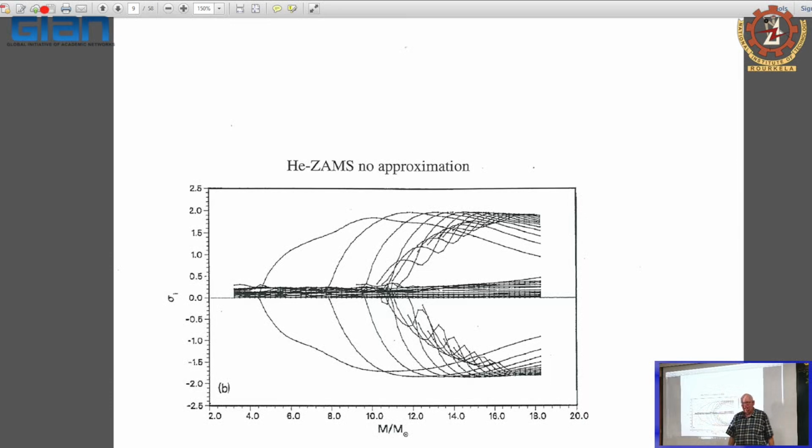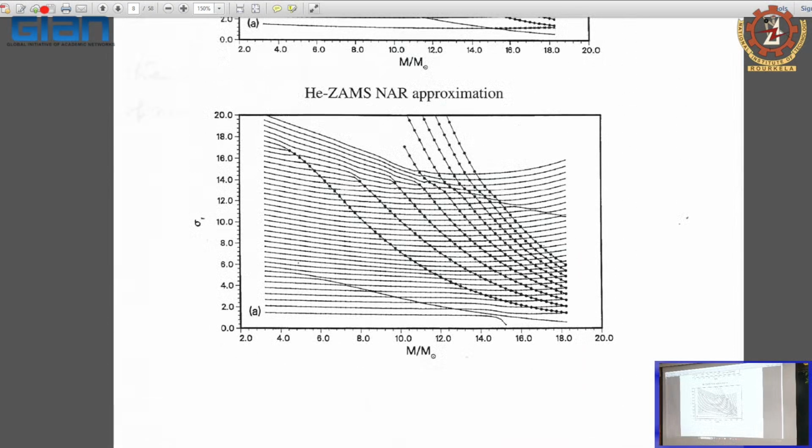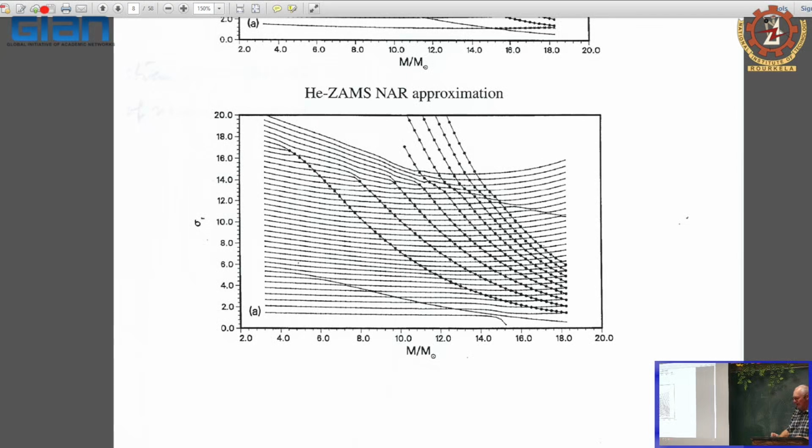These modes actually have almost the same real part, the same frequency. It is not that obvious because below or close to these thick dots, which denote the unstable modes, there is a tiny dot which belongs to the mode with the almost complex conjugate value of sigma I. So these lines denote two modes, one of which is unstable and one of which has a high damping rate, and they appear in the imaginary parts as complex conjugate pairs.